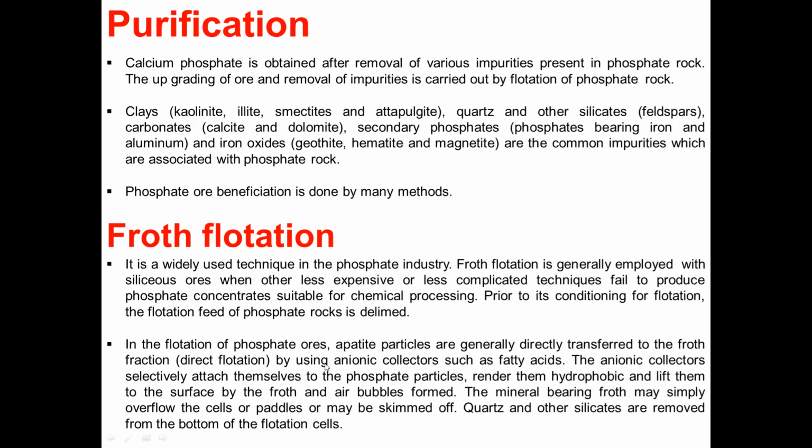That is direct flotation by using anionic collectors such as fatty acids. The anionic collectors selectively attach themselves to the phosphate particles, render them hydrophobic, and lift them to the surface by the froth and air bubbles that are formed. The mineral bearing froth may simply overflow the cells and paddles or may be skimmed off. So mineral is skimmed off. Quartz and other silicates are removed from the bottom of the flotation cell.